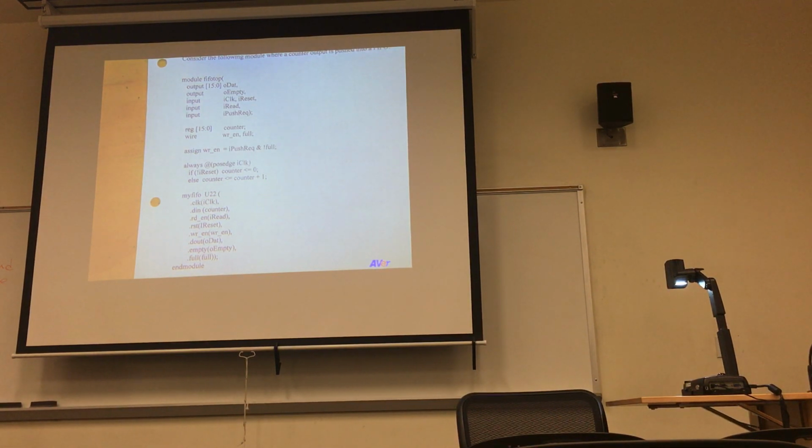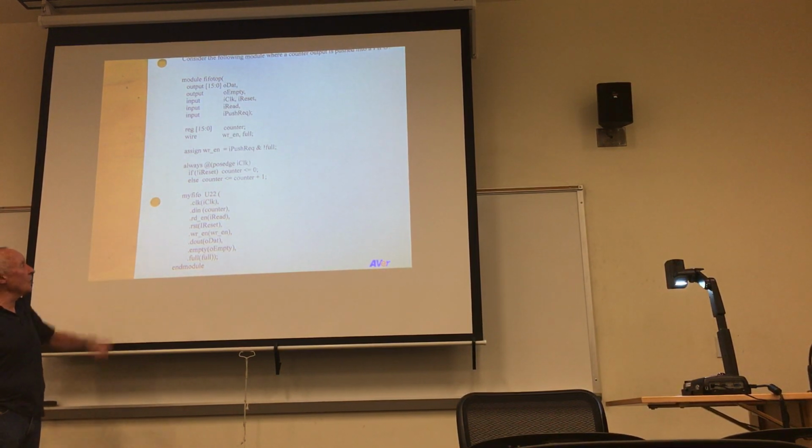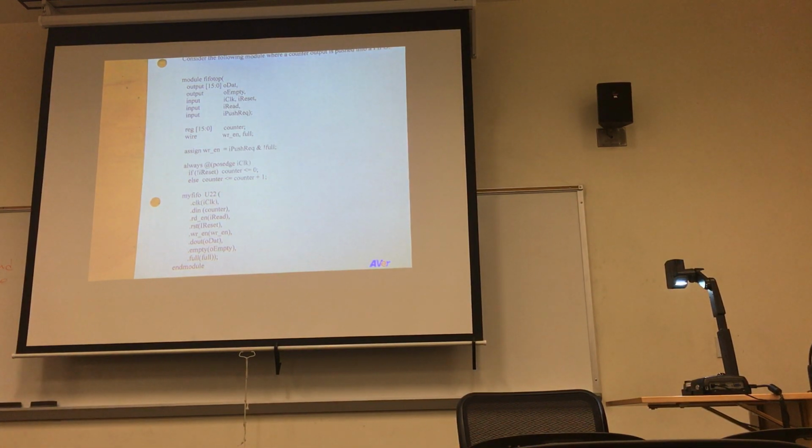And this is a 16-bit count. Okay. I've also instantiated in here a module myFIFO, and I've got connection by name. And I'm assuming that myFIFO was generated by an IP generation tool. So that IP generation tool will give me a behavioral file, .v file, which I can use to simulate to verify that this FIFO top module functions correctly.